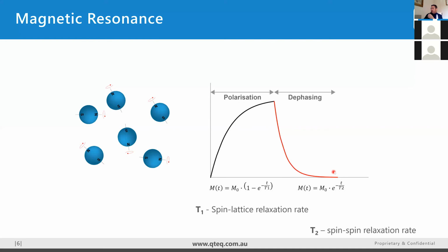Transverse relaxation, or your CPMG measurement, is just a lot easier and quicker to measure downhole. So for T2, our logging speed is typically 1 meter per minute. For T1, it will be a lot slower than that.